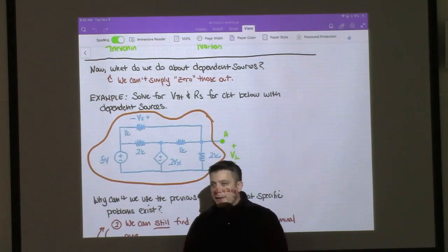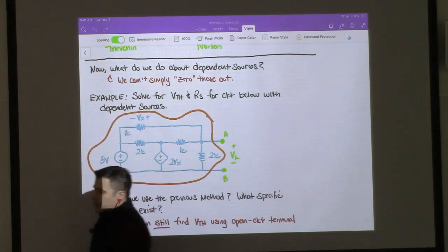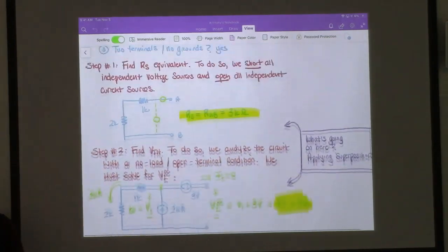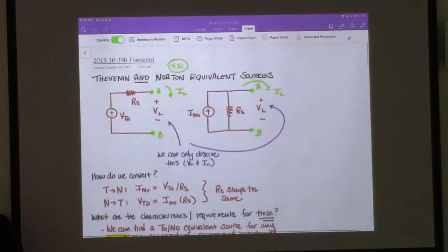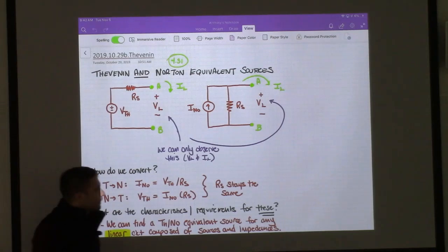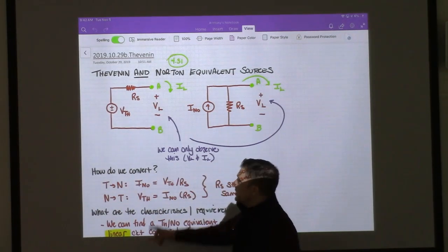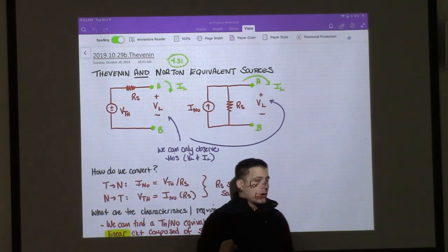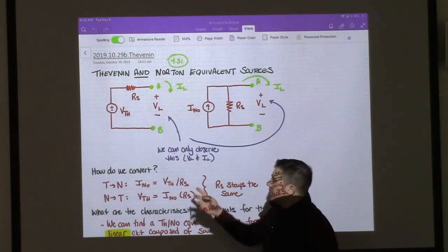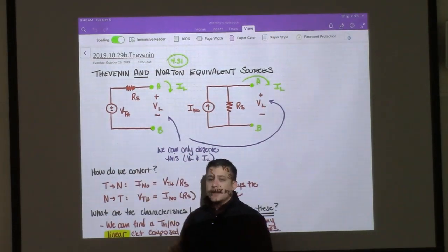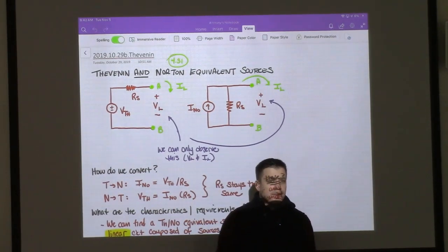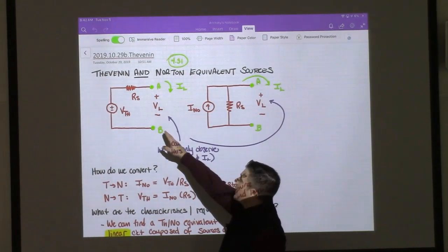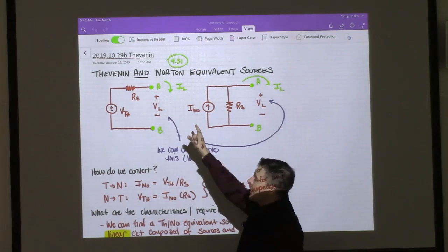So what do we know about the Thevenin? If I scroll up for a second here, if you take a look, what you see is that the voltage observed at the terminals, which we're calling VL, is the same as the internal voltage Thevenin, as long as there's no current IL flowing, right?